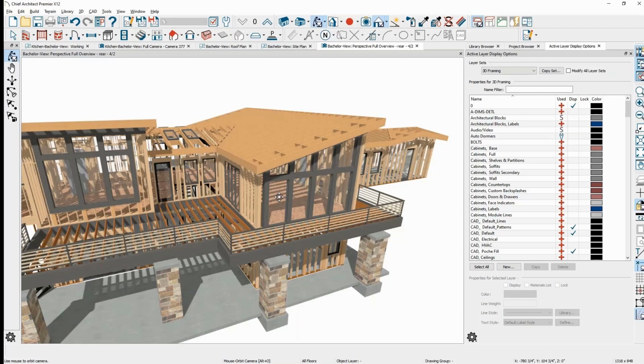then you've got to do double studs, which is easy enough. Because what I do is, instead of having my studs at, you guys say 2x4, we typically say 4x2. What I would actually do is make my studs a 4x4, so it represents that you've got a double stud. But then occasionally they'll actually call for your blocking to be at 600 centers for a particular wall for wind loading.